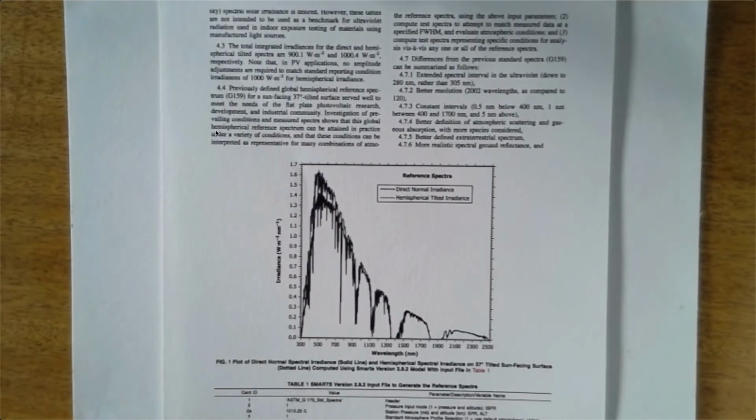more nuanced spectral responses. Unfortunately, existing multi-junction cells are typically designed and rated and optimized with a standard solar spectrum. So this is a typical solar spectrum used within the photovoltaic community. It's from the American Society for Testing and Materials. It assumes, among other things, well, first of all, it's fixed, right? So independent of climatology, it's fixed. It assumes an air mass of 1.5 and a low aerosol optical background, which can be very unrepresentative of the actual climatology in which many of these solar panels are being deployed.